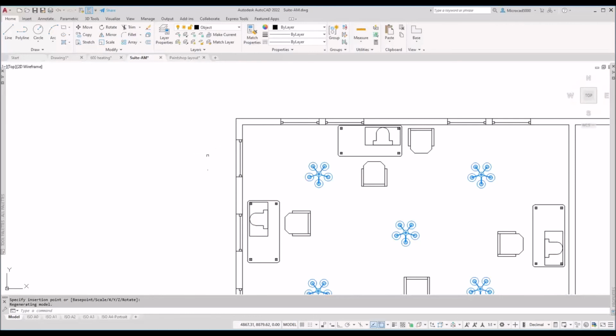Now, what you guys might do already is to offset this line down over and offset this line across to get a construction line down here. If they were crossing, you might have moved them as well to find that point. But what should I do here with this tracking tool? I can go to my circle command here and say, draw a circle. And the command line says, where's the center point?